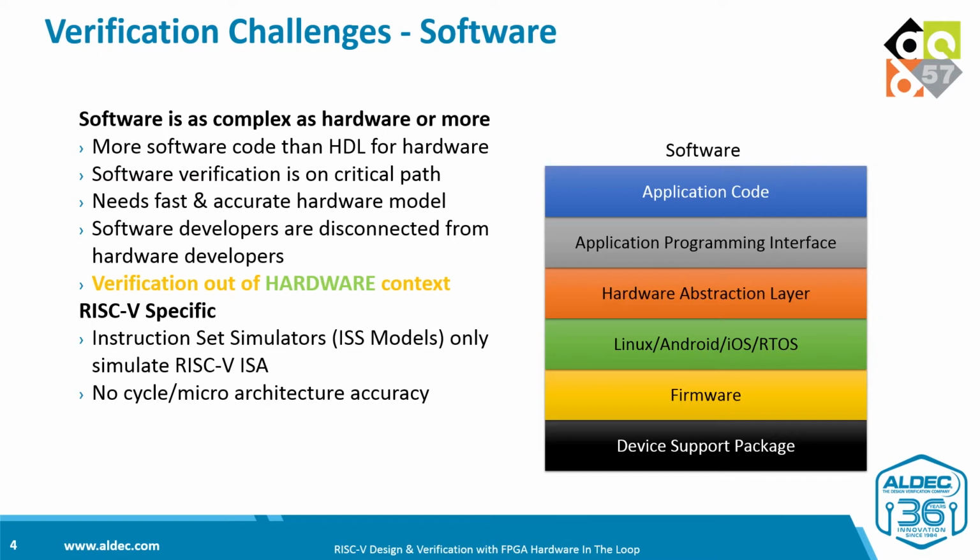For example, you can create a simple microcontroller level performance core, or you can create a high performance superscalar processor, and both will provide the same RISC-V ISA. The difference is in the microarchitecture, which is not reflected by the instruction set architecture.